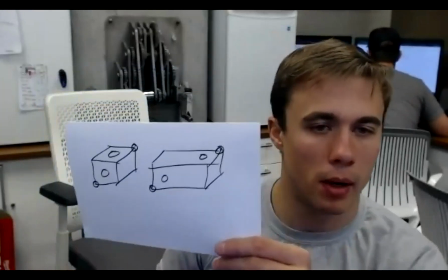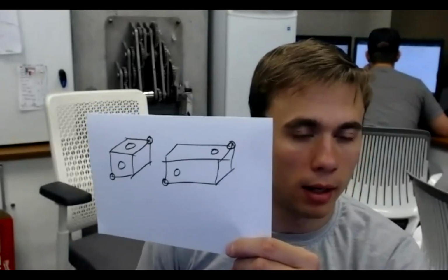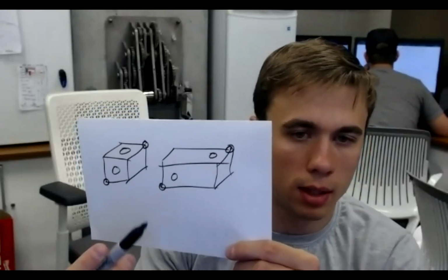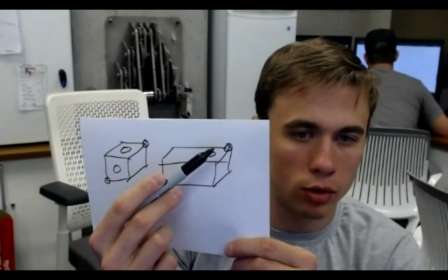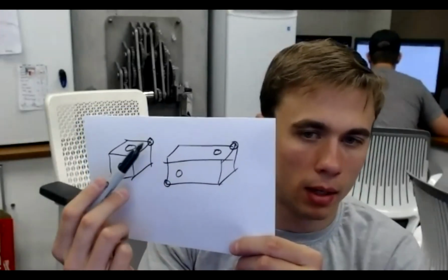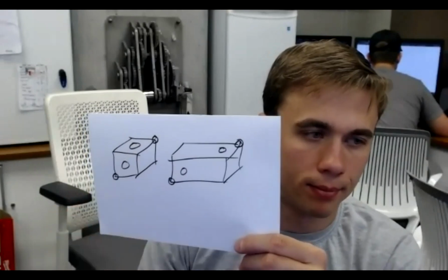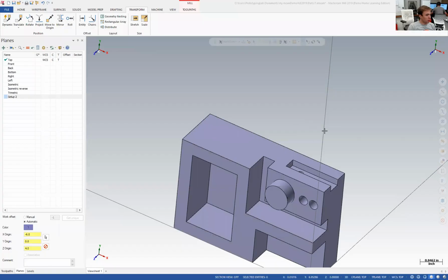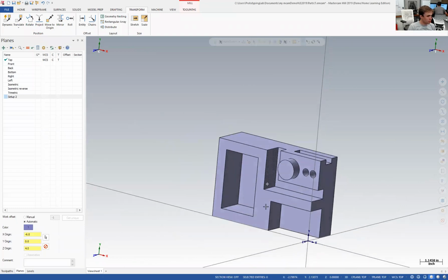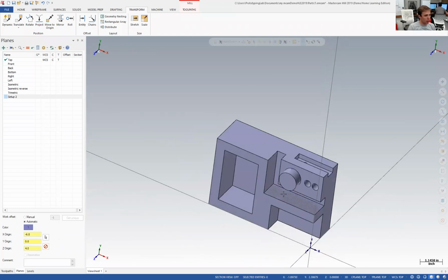Now, obviously, when you make parts, your error is much more like on the order of thousandths of an inch, not inches. But you can see that if I drilled through here and then drilled down here, they don't intersect at all where you want them to in this setting. There are a lot of different ways that this error can manifest, but the short of the long is you want to try to get your datums to share as many planes as possible. So coming back to MasterCAM, the datums we currently have selected are okay, but not great.